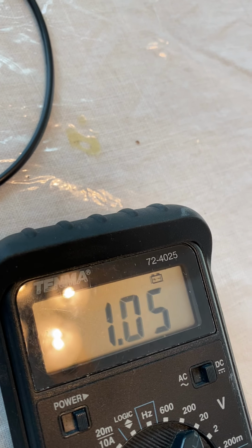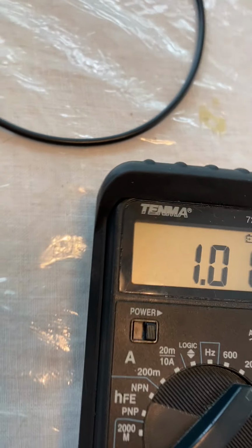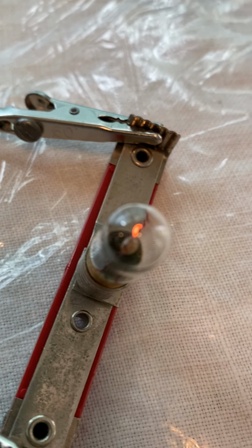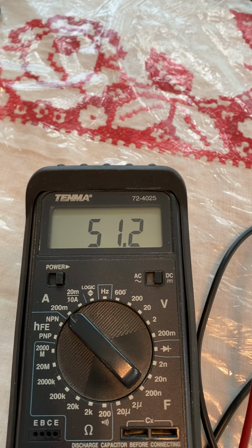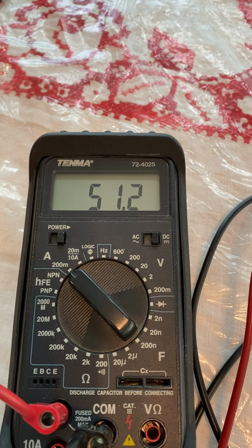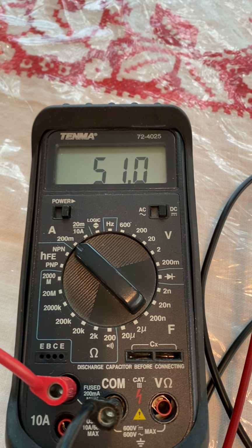All right. So we're at 1.00 volts. And you notice we're already getting a little bit of light through. The current, again, this is in milliamps. When you enter it, you're going to want it to be in amperes so that when you're calculating the resistance, you're getting a reading in ohms.